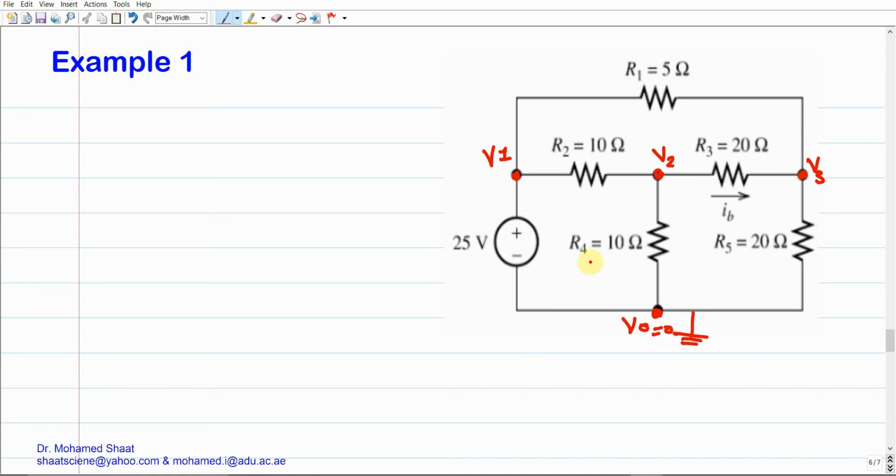How about the fourth step? The fourth step is very simple. Locate the elements. How many electrical elements do we have here? We do have the voltage source. This is one element. We do have this resistor. We do have another resistor, and in total 6 elements within this electrical circuit. All of these are different elements, and this is step 4. Just locate the elements. Step 5, assign element voltage. For each one of these elements, give a voltage. But this voltage should be an element voltage, not a node voltage, right? So for example, I can give this element a voltage, a name like Vx, for example.